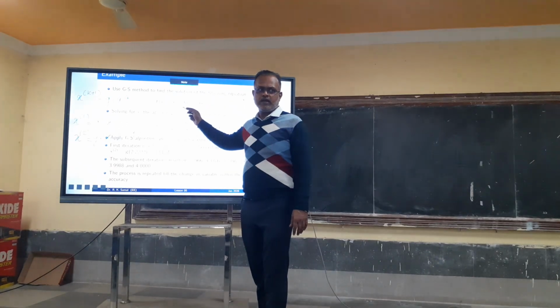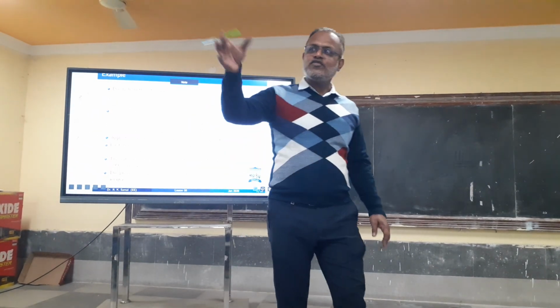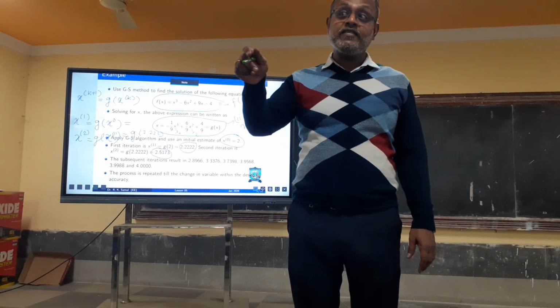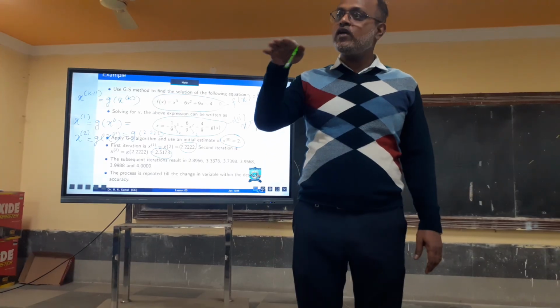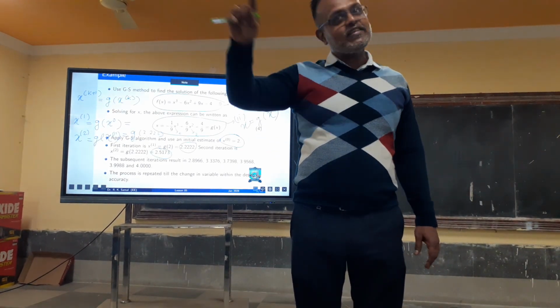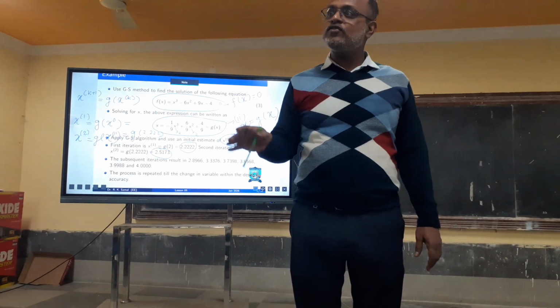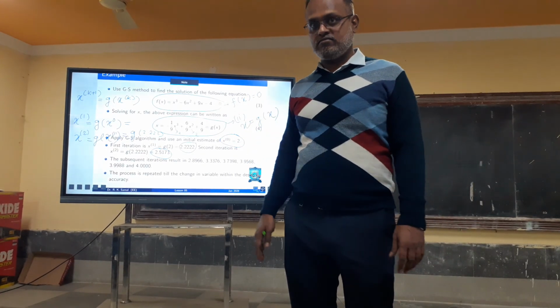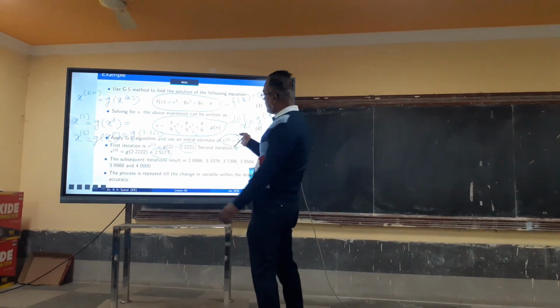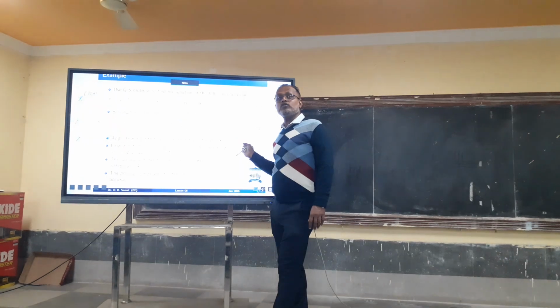Now the point is that if you start with a different initial guess, you might get a different solution, which can be wrong, which happens most of the time in power systems. You gave a wrong initial guess, you get somewhere which is actually a solution, but it is not a feasible solution. Now, by chance, we have taken an initial guess very near to a feasible solution.